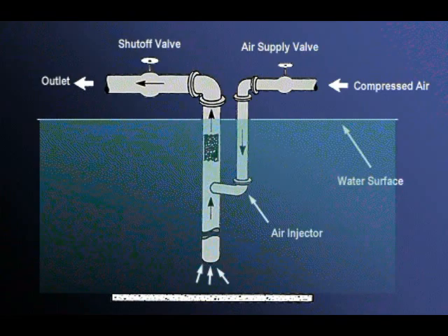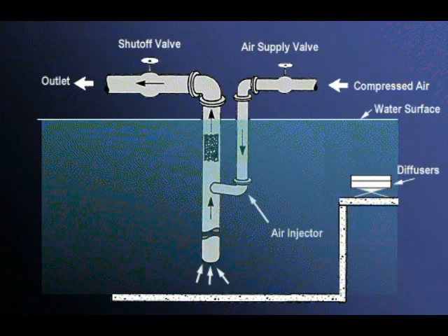The air supply valve in the diagram must be adjusted with regard for both the pumping rate and aeration requirements. With more complex systems, however, valve adjustments may not be sufficient to correct pump function and further investigation may be required. Conversely, if the air injector pipe is lower than the diffusers, the airlift pump may not get enough air. This can be corrected by raising the air injector or throttling the air supply line to the diffusers or isolating the two supply lines.